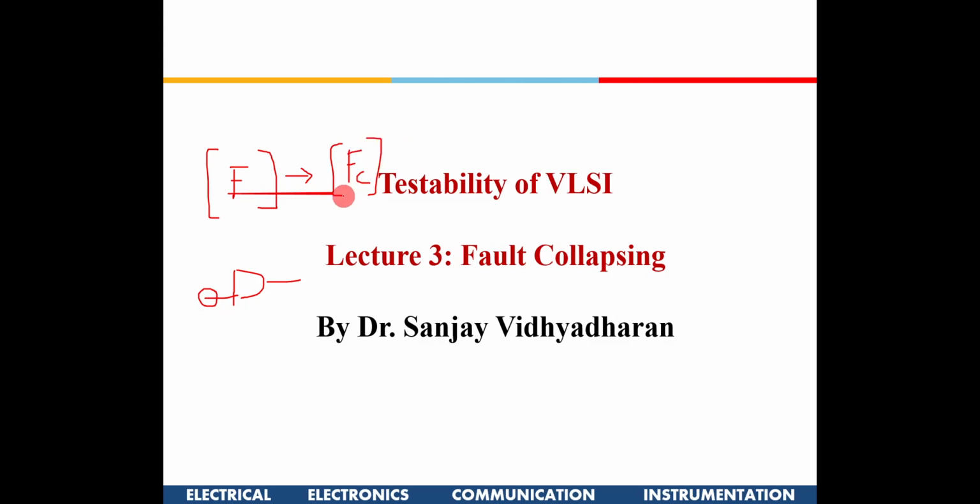Now after doing the fault collapsing, generally these faults we categorize into 2. Some are difficult to detect and some are easy to detect. We are going to run some algorithm which will classify these faults into 2 categories. Now for these easy to detect faults, we are not going to take each fault one by one and try to find a test vector for it.